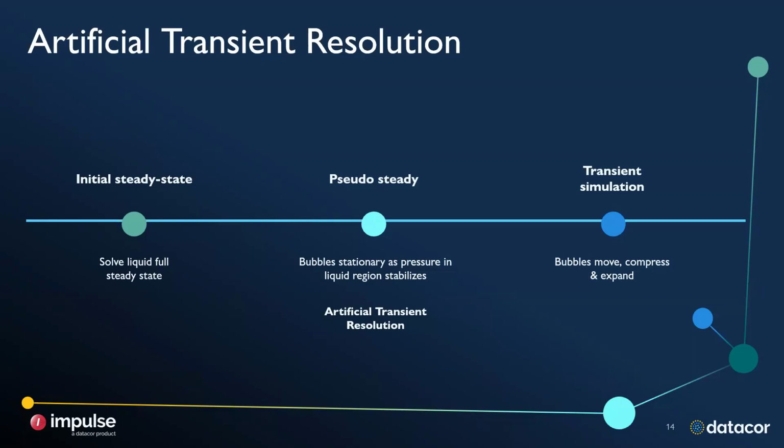So once it hits this stage, the fluid volume in tanks and accumulators can change, and the transient events you specify for your junctions can start to occur. The gas-liquid interfaces can move in this stage, and gas pockets can now expand and compress. And more massive gas can enter and exit the system.